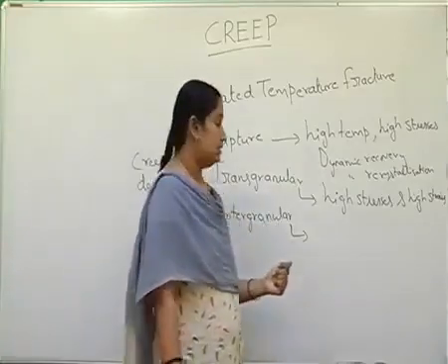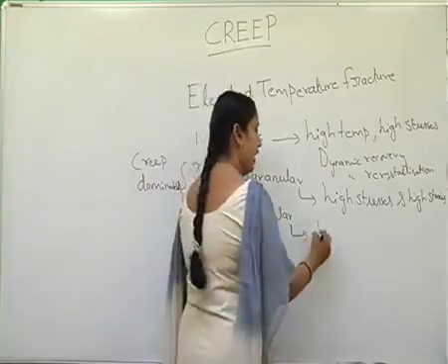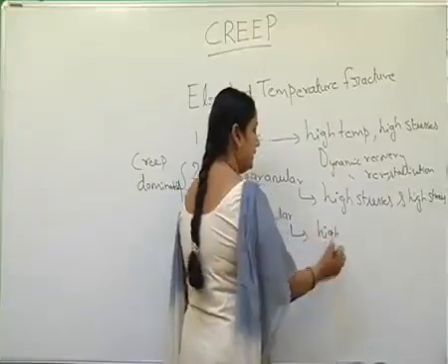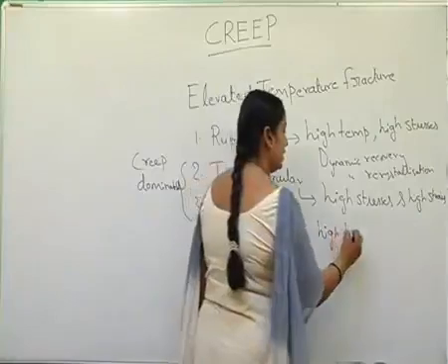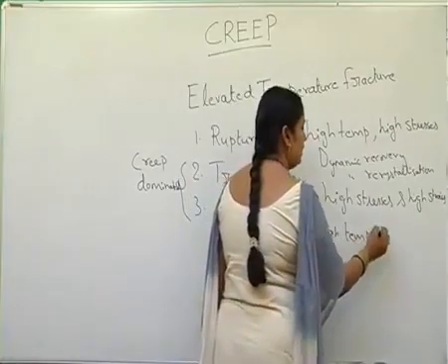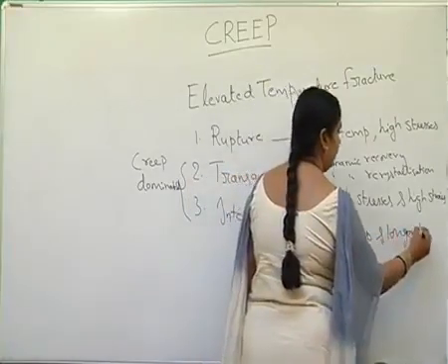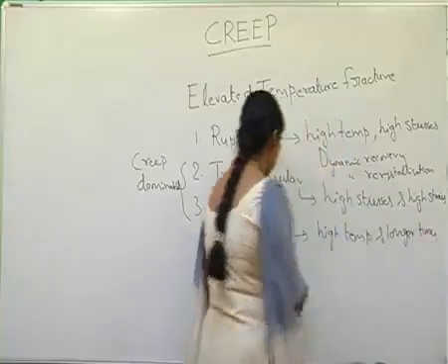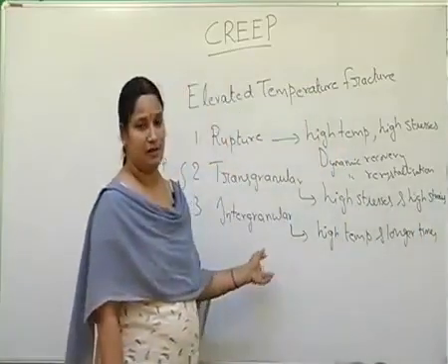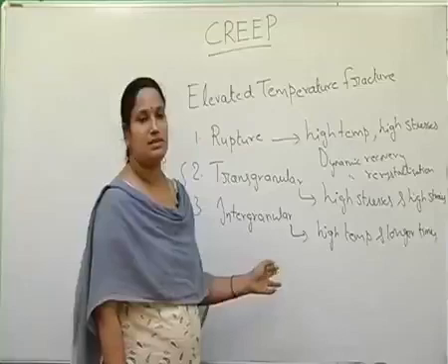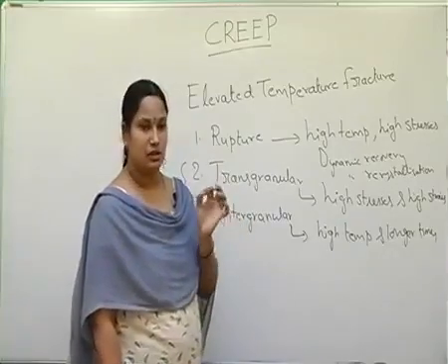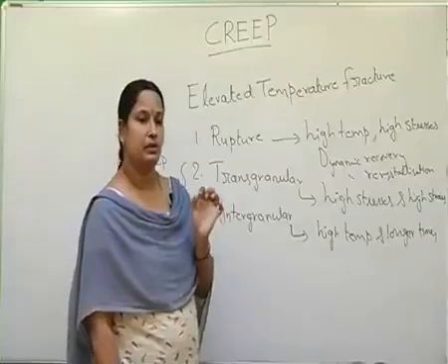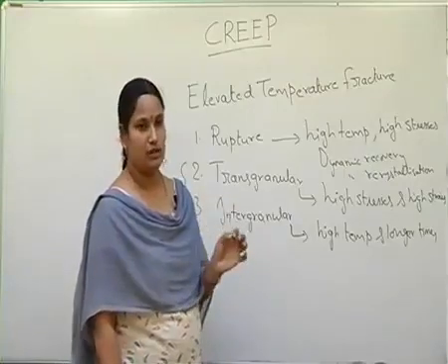intergranular fracture, this occurs at higher temperatures than the transgranular mode of fracture. It occurs at high temperatures and longer times. This type of intergranular fracture also occurs by the nucleation or formation of voids around the inclusions.